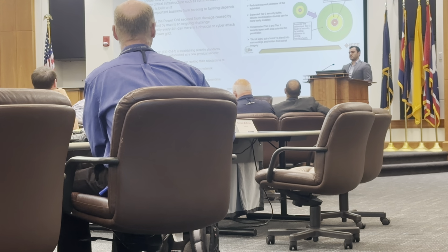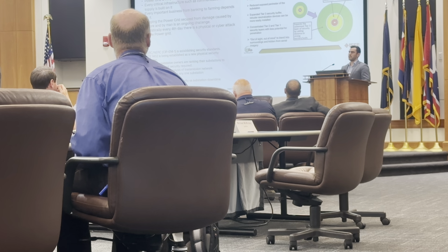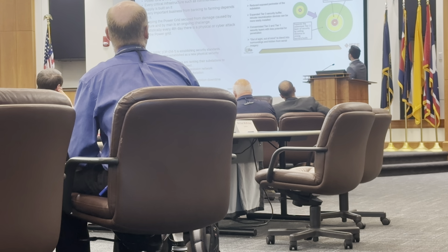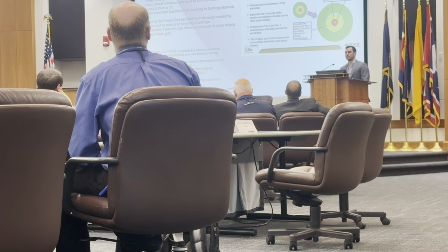Physical threats in substations are real. The grid is very important to society, and any terrorist attack would be a risk when you have AIS substations. So the GIS does have that added level of security, that extra shielding, when you keep it inside a building. It's not as prone to bullets, and it's not as prone to any type of malicious attacks.